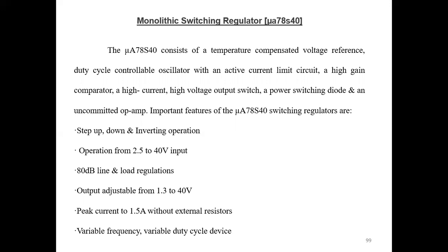So operation from 2.5 to 40 volt input. 80 dB line and load regulations. Output adjustable from 1.3 to 40 volt. Peak current up to 1.5 ampere. So it is a variable frequency, variable duty cycle device.